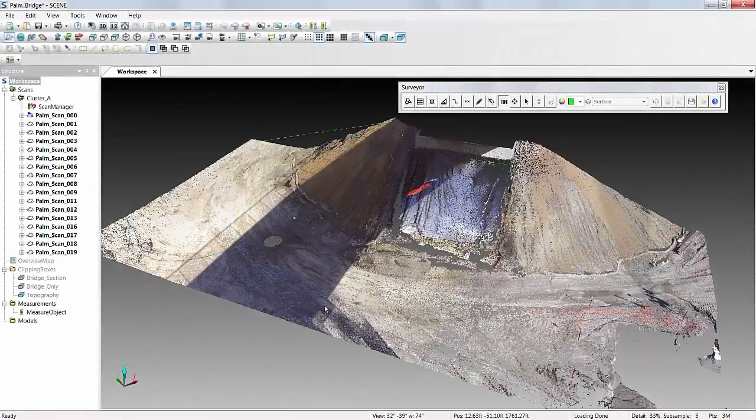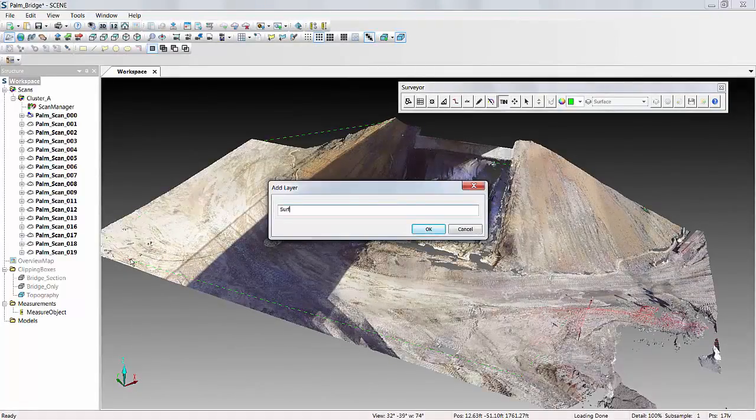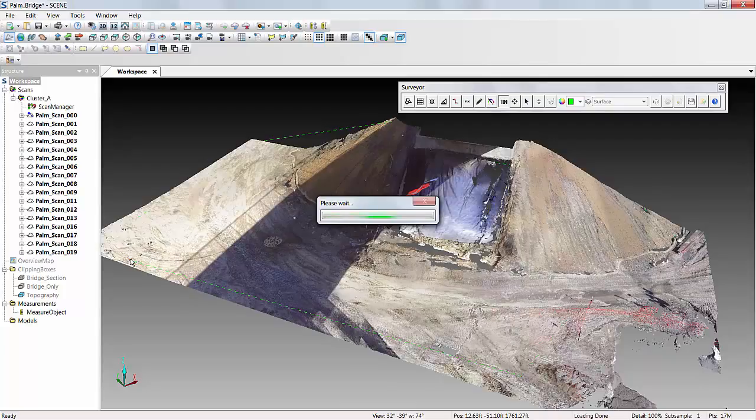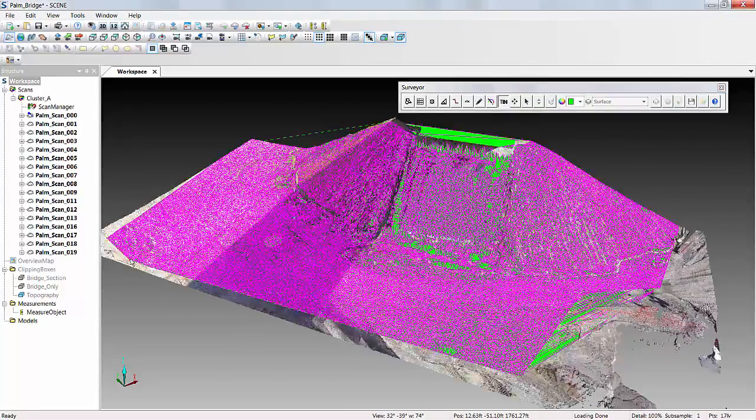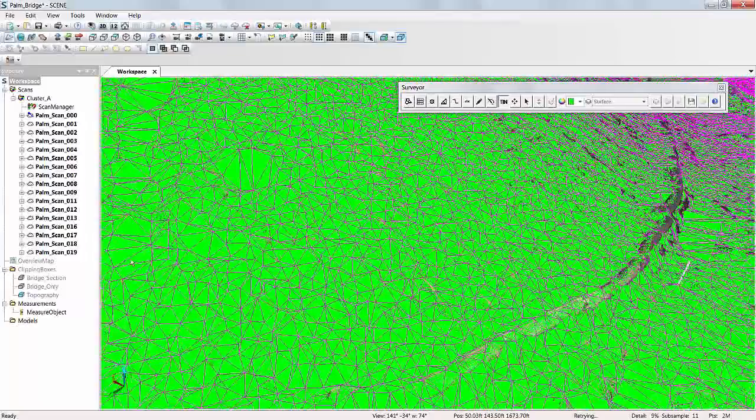Surfaces. So of course for our buttresses, we were able to just capture that along with the rest of the bridge that we happen to be capturing, and using the builder or the surveyor app can produce a TIN surface directly inside of Scene that we can then export to LandXML.